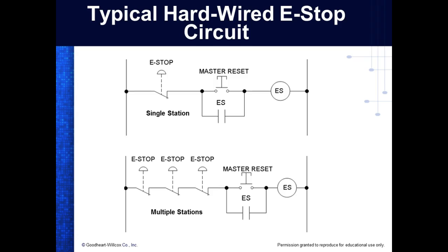By the way, I couldn't find the ANSI symbol. This is actually, I'm sorry, this is actually the ISO symbol for e-stop buttons, the international standard for e-stop buttons. And notice it's got this mushroom head on it. You can't have a guard around it, right? You understand that? You can't have somebody have to pick up a guard to hit an e-stop. So these things have got to be out. They've got to be red. Some of them are lit, right? Some of them are lit.